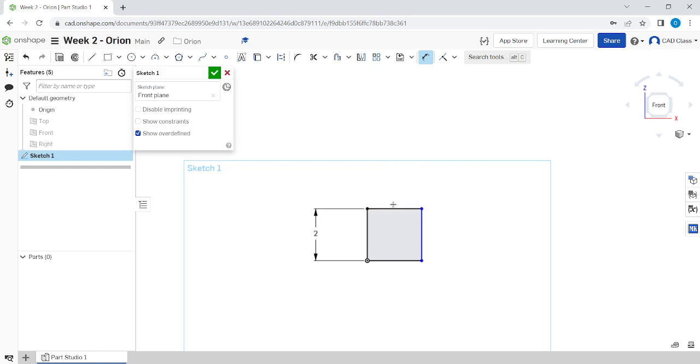Sometimes you don't have a line that you can dimension the length of to set the distance between 2 sides of some shape. So what you can do is click on one, and it'll start creating the label like it did before. But I don't have to click to place the text down. I can click on another piece of geometry, another line over here. Now you'll notice it's dimensioning between the two. Now I still need to place my label down.